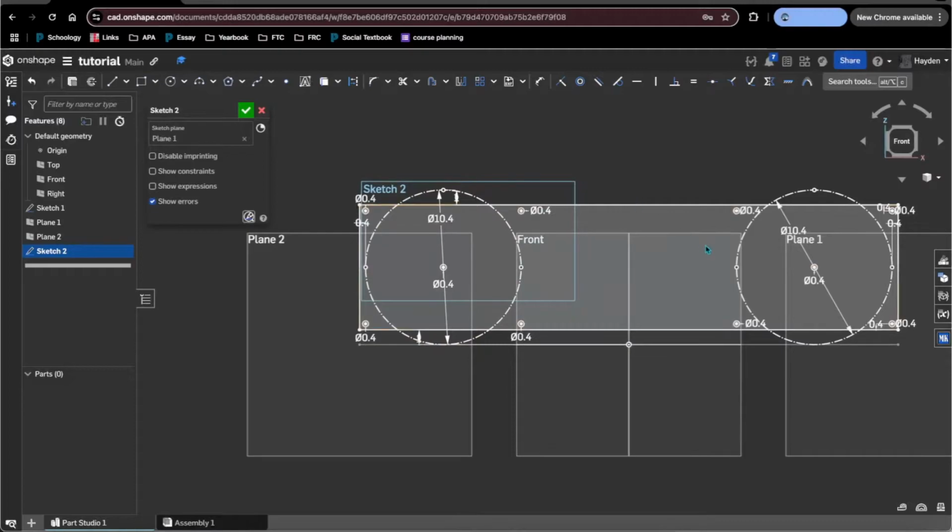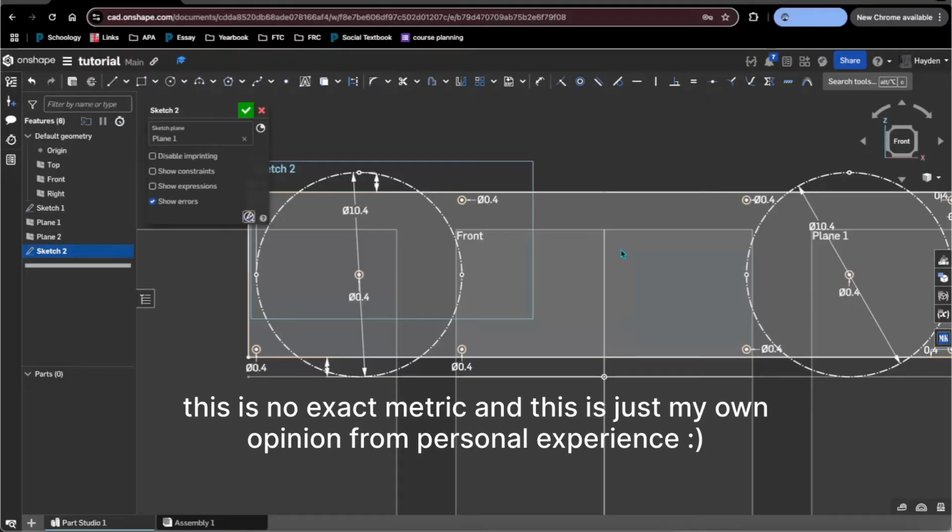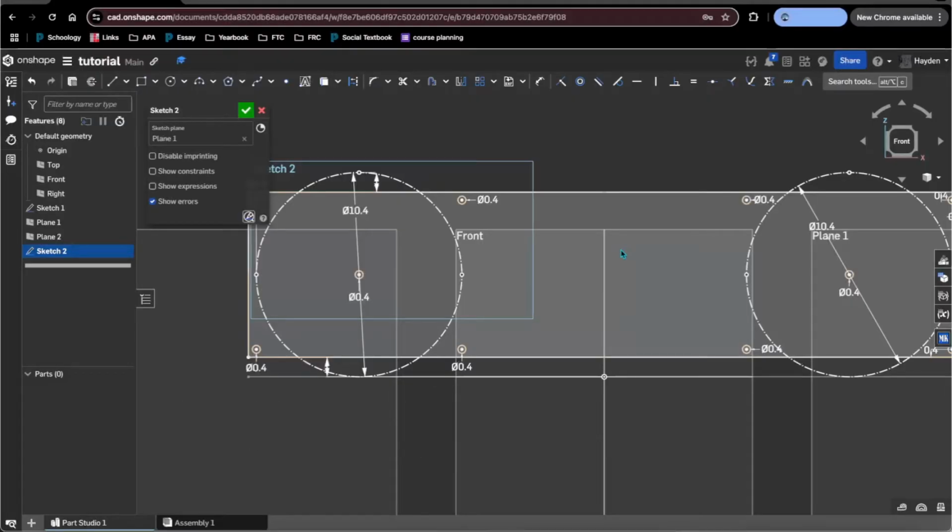Okay, now that we've done that, we're going to add the screw holes for our motors. And this is going to be where things get rather complicated. You're going to have to memorize the dimensions a lot for these, but once you've made tons upon tons of drivetrains, which is essentially the way that I recommend you learn CAD, you can watch this tutorial as much as you want, but I would say you should only really start CADing a robot once you have been able to freely CAD a parallel plate drivetrain without a tutorial.